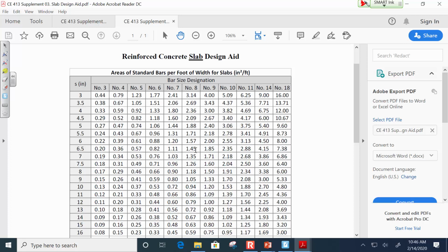So what you'll do is you'll go in and say, okay, I need this steel, find the pattern that gets me as close as possible. Now there's a lot more resolution with slab design than there is with beam design. Remember, with beams we had like 1.84 and then 2.21 and then 2.41, a big gap between those numbers. Whereas here, you can see I got a 0.72, a 0.71. If you look at your efficiencies for slab design, they'll be like 98%, 99%, because you can get slab design to be a very, very efficient design. That'll become clear next time when we do a problem.